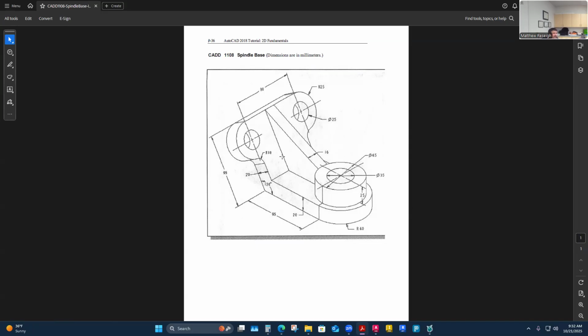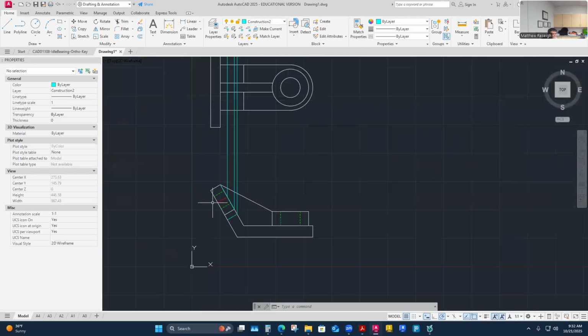Our ellipse command, you can draw it several different ways, but one way to lock it in is if I can lock in the center and I know the extents of the major and the minor axis, which is what I'm going to try to block in up top. So I'm just focusing on getting what this looks like up top. It's 50 millimeters this way, and then this way I want to know where my intersection point would be. So let me come back here where the center of that would be.